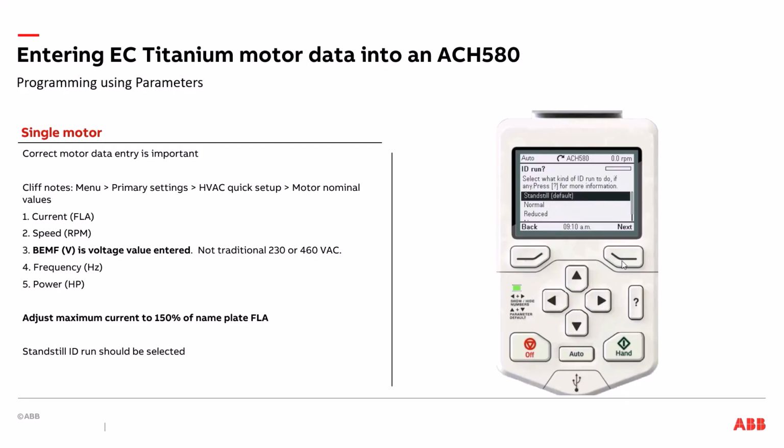Click Next. And it's going to ask you, do you want to adjust any of these values for the tune to a different value? These adjustments would be useful if you're going to have to do a rotational tune, but since we're doing a static tune, we don't have to worry about making adjustments. If you want to, you can just set the values as permanent. Since we're not changing anything, it's not going to make a difference, but we could just select set values as permanent.